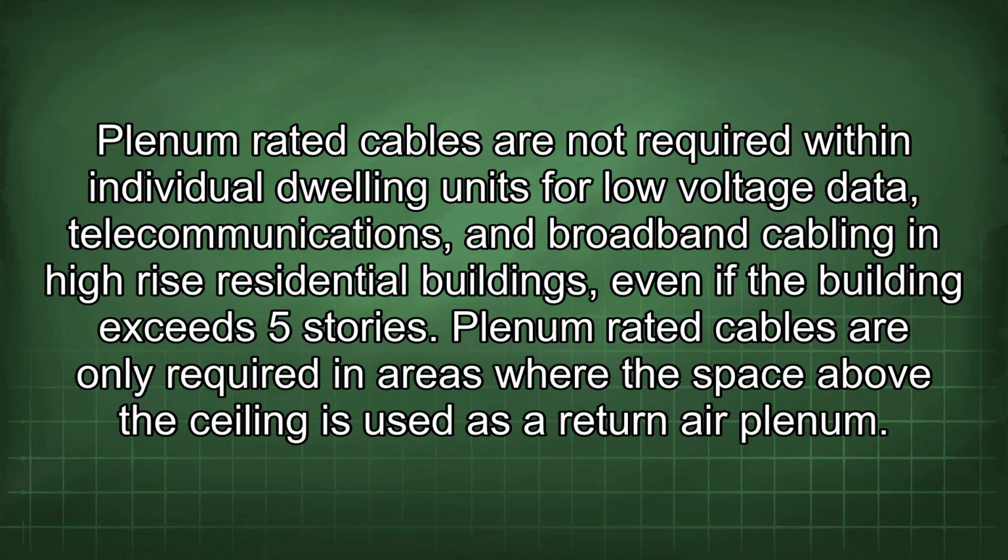Plenum-rated cables are not required within individual dwelling units for low-voltage data, telecommunications, and broadband cabling in high-rise residential buildings, even if the building exceeds 5 stories. Plenum-rated cables are only required in areas where the space above the ceiling is used as a return air plenum.